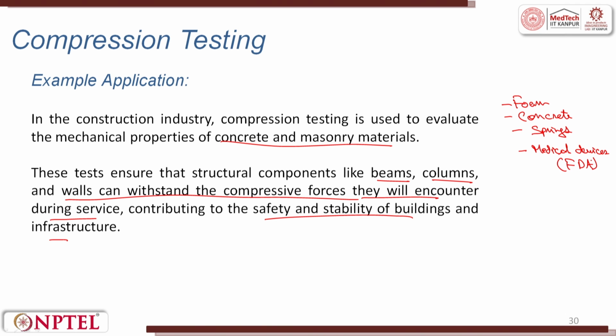Compression testing can be conducted using a diverse selection of platens specifically engineered for different types and sizes of specimens. This method is employed to assess characteristic values including elastic and proportional limits. We calculate the yield point, yield strength, compressive strength, and obtain further mechanical details in the testing, so that we can apply the material to actual use.